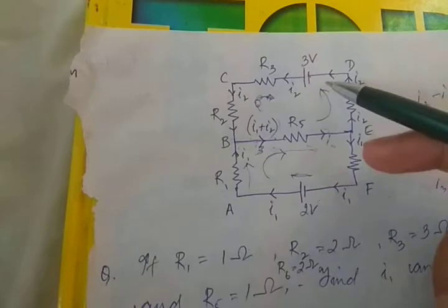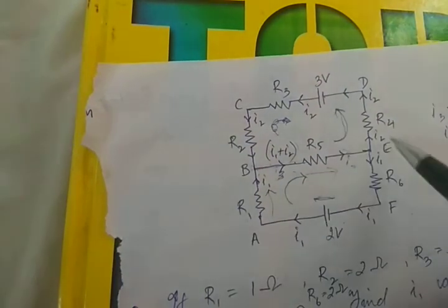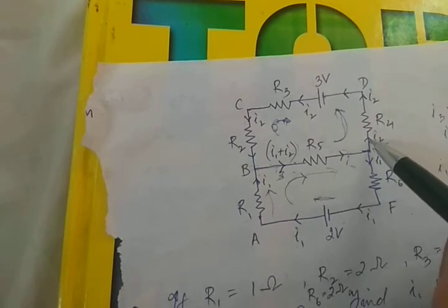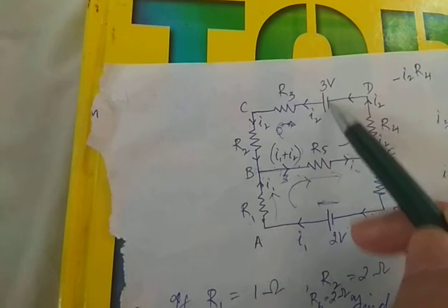All right, anti-clockwise direction of movement, I'll write the equation itself over here. Let us first come across this resistor R4. We've taken anti-clockwise direction of movement. Now we see that we are moving in the same direction as the current I2. So here also we are moving from higher to lower potential. So potential difference across this R4 will be minus I2 R4. Then we come across this battery, and again we are moving from negative plate to positive plate.